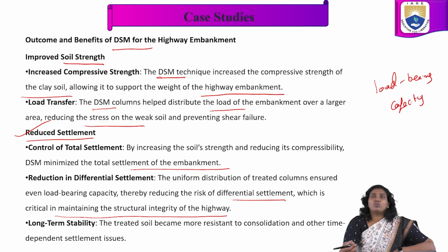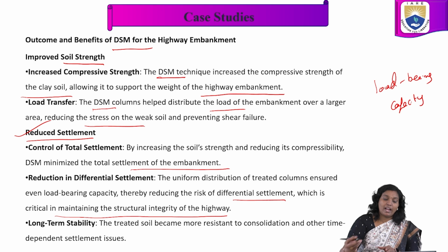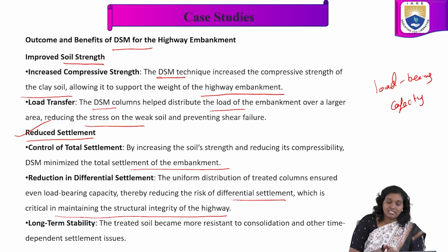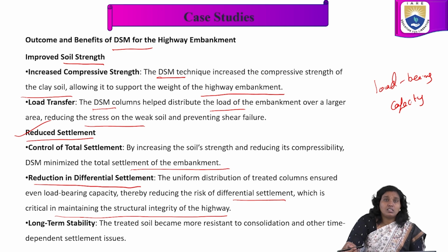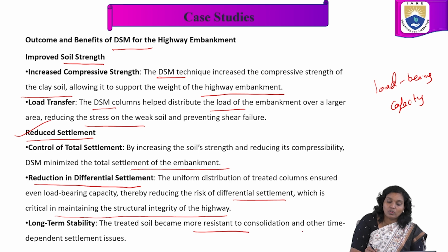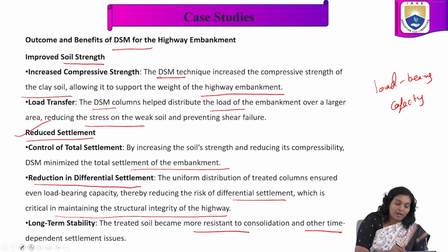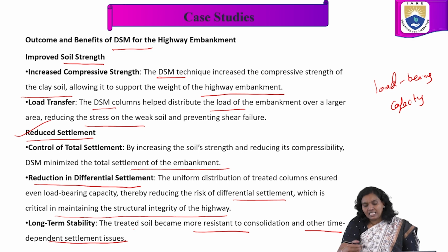So thereby reducing the differential settlement, which is crucial in maintaining the structural integrity of the highway. In long-term stability, the treated soil becomes more resistant to consolidation and other time-dependent settlement issues. So these are the parameters which we are going to understand.